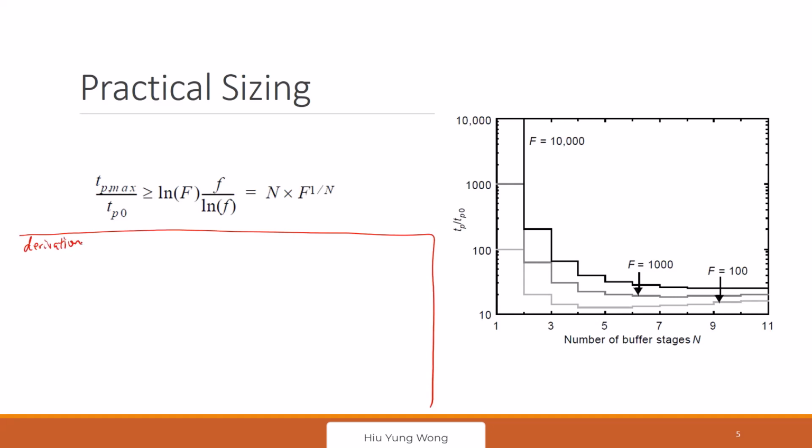Right. What is the delay of an inverter? Right, practical sizing. Do you remember what we're talking about? We want to drive a very huge capacitor. Remember, very big cap, off-chip cap. So if I want to minimize the delay, last time I showed you that it's going to take maybe 2mm size transistor in order to minimize the output.